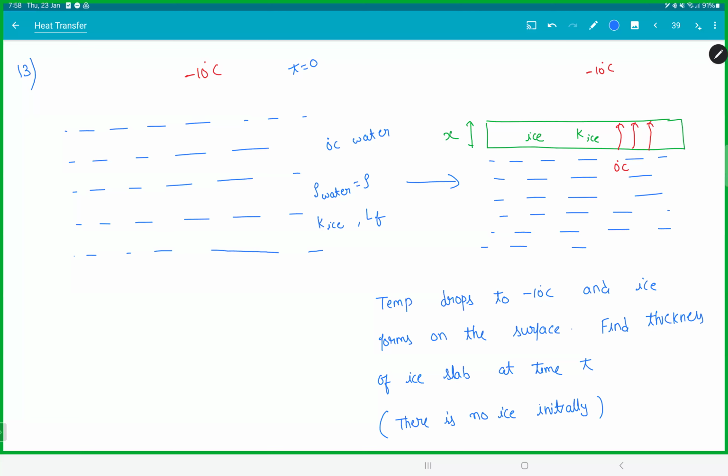Ice will obviously be at 0 degrees, right? Unless all the water freezes, you won't get lower temperatures. Remember, ice temperature can't drop until everything becomes ice. The lake is still unfrozen, right? There is still some water. Start like that. After time t, let the thickness be x. Let dq heat flow out. Let the ice thickness form dx. That's how you always start. Think. I'll give you a minute or two.